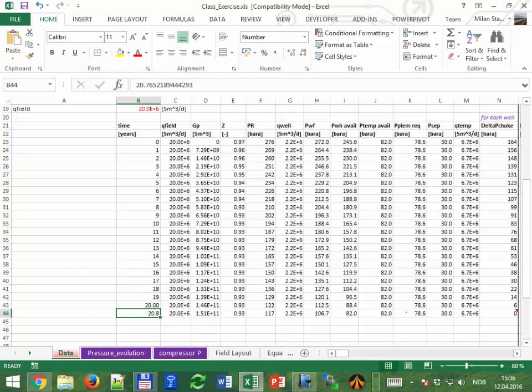Do you remember? We were doing it in the choke, okay? So we were doing our calculations from the reservoir all the way to the wellhead. That's the available pressure. And then we did required pressure from the separator, pipeline, flow line, and then template, okay? But now this point, it's not going to be different because the choke is fully open. The two pressures are going to be the same. So we're going to move the point to the plem.